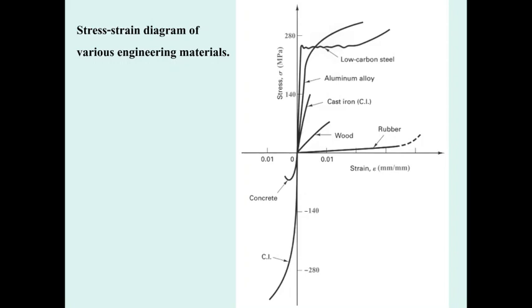mechanical property, because concrete is produced by mixing Portland cement with water, sand, and crushed stone. When mixing, the concrete has air voids in it and some cracks in it during the process of hardening. If you pull the concrete, the cracks and air voids are going to grow very quickly, so the concrete can take only a small tensile stress.